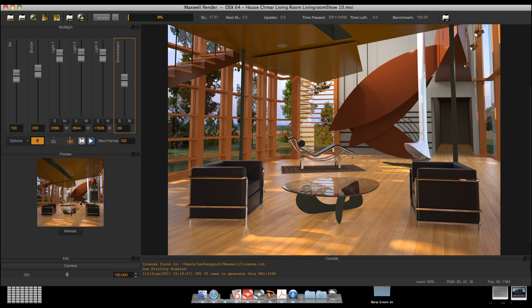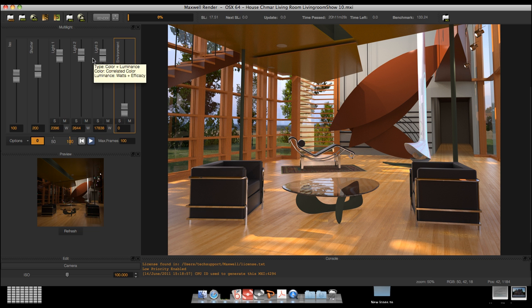If I look at my preview here, I can go ahead and slide this environment slider down to 0. I want it to be nighttime, so I don't want any sun or environment. And I also have these lights that I've added throughout the scene, so I can use these to basically season my scene by looking at it down here in the preview until I have exactly what I want.